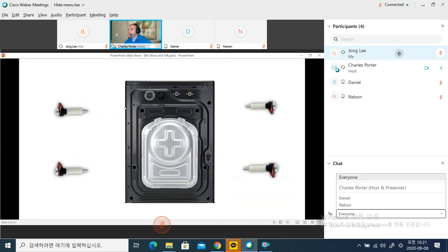They go through those holes, screw into the back of the outer tub, and secure the outer tub to the cabinet, so that when this thing is shipping, bouncing around inside the back of a truck, that tub inside is not shaking around real bad and possibly getting damaged during shipping. These need to be removed as soon as the unit is installed, before the customer can use it. But the unit will work with them in there, unfortunately.